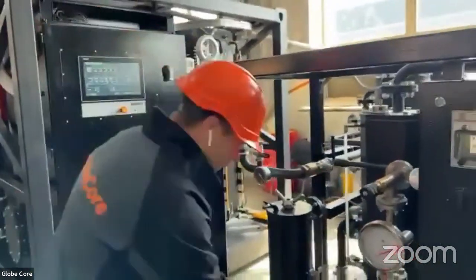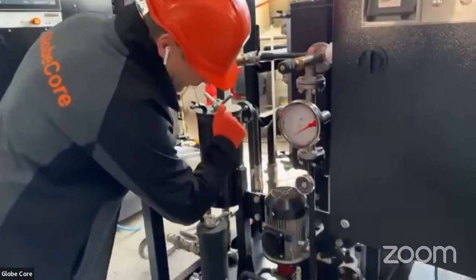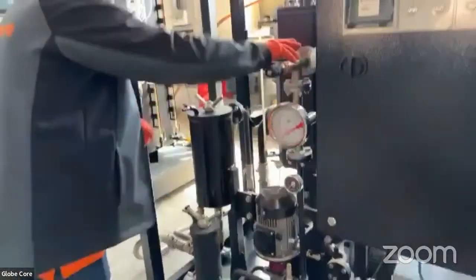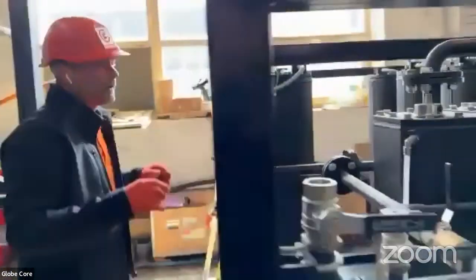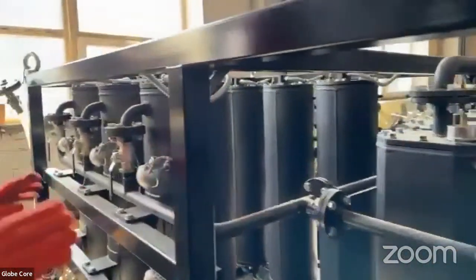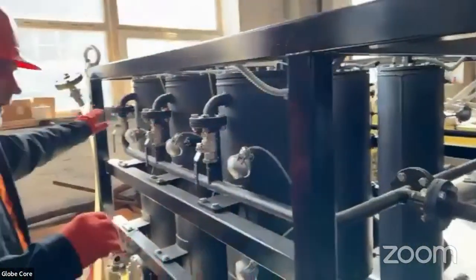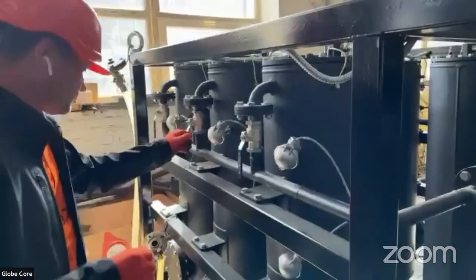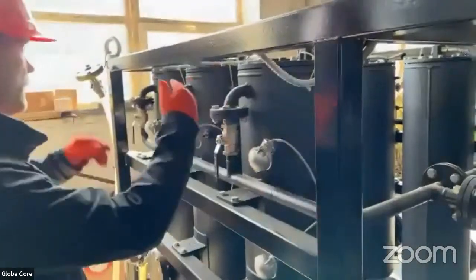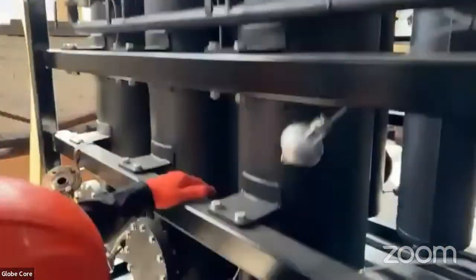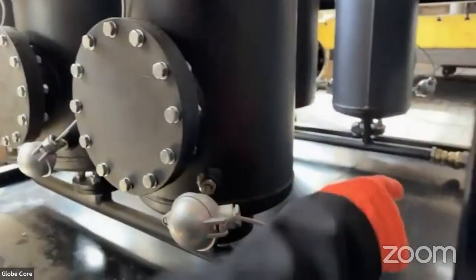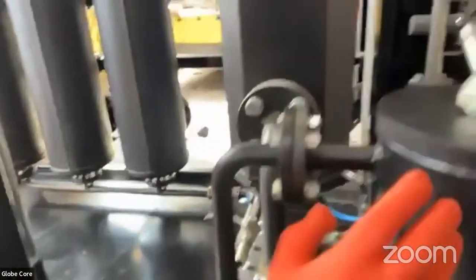So, the oil pump pushes oil through the adjustment valve into the wings of regeneration columns. We have two equal wings, each of 3 columns with valves. Oil goes in the direction from the top to the bottom. Then it is collected in this manifold and passed into this line to the fine filter.